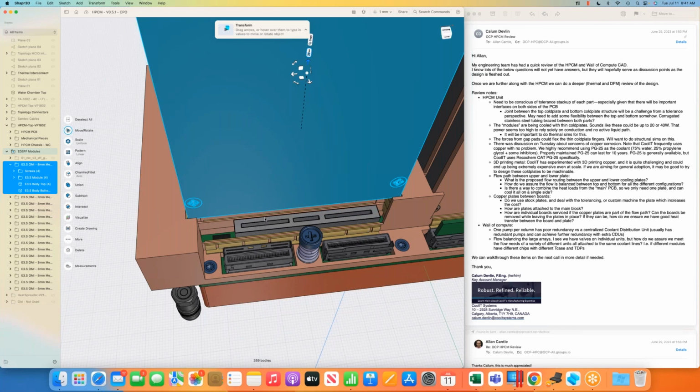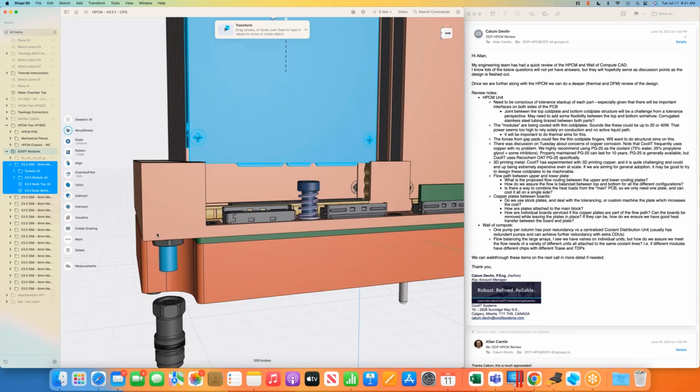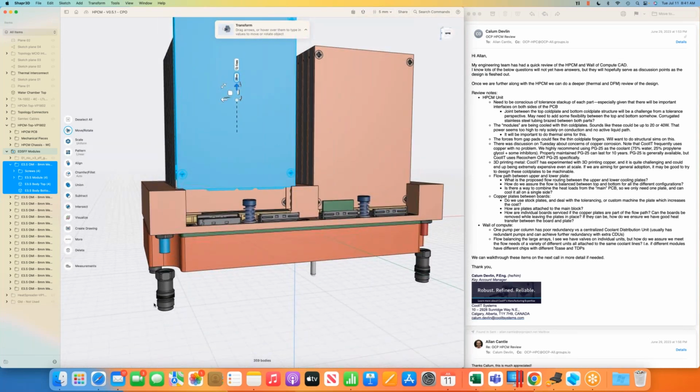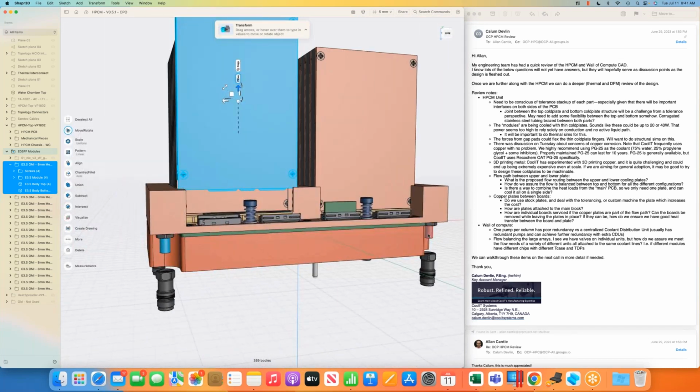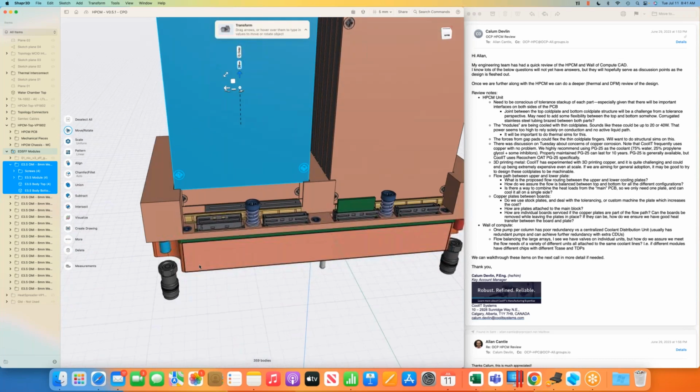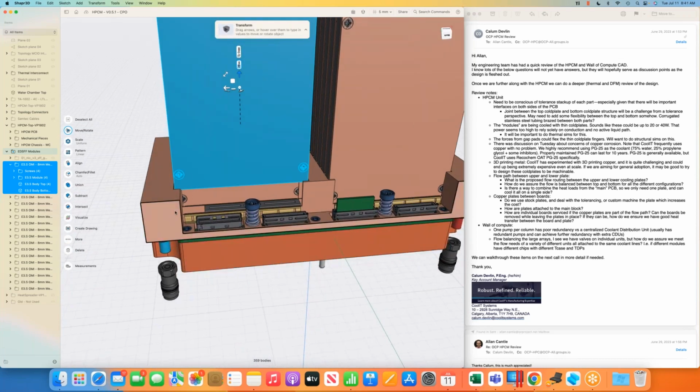With this setup, is there water coming to the top of the module? How do you evenly distribute the heat in the entire module? So the water comes in here, the blue is cold, so we've got 2 inlets at this end and we've got 2 outlets at this end. It comes directly into these modules first and it flows down all of these veins.